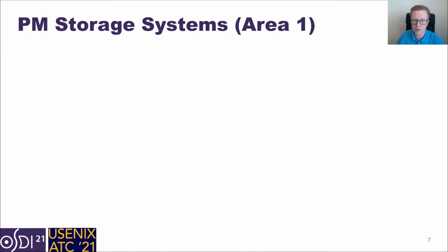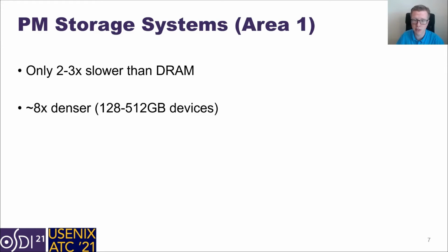There are a number of interesting characteristics of persistent memory to consider when designing persistent data structures. First of all, as we discussed previously, persistent memory is not quite as fast as DRAM, but still has access performance far faster for small reads than SSDs, and so many persistent data structures are designed to be accessed and modified directly on persistent memory. This is unlike block storage devices, which usually require page caching in DRAM, requiring more block-centric designs. Persistent memory is also denser than DRAM. Intel sells Optane in 128, 256, and 512 GB form factors. This is denser than DRAM, but not as dense as SSDs or large hard disks, and so some trade-offs may need to be made based on the targeted dataset size.